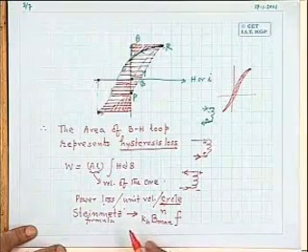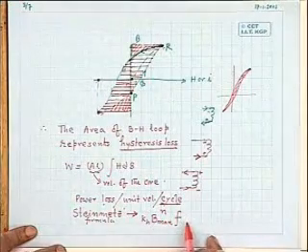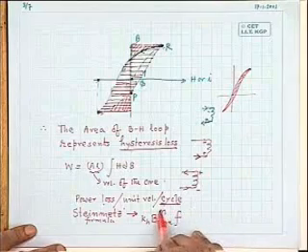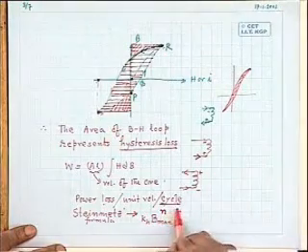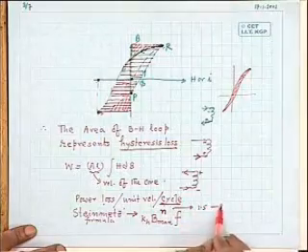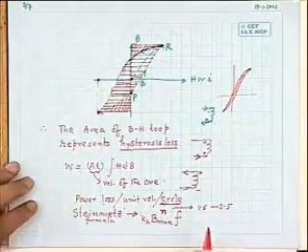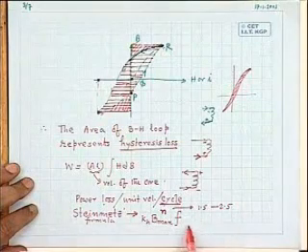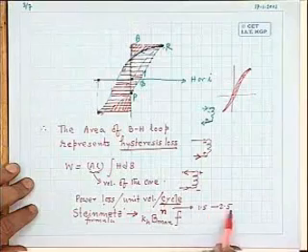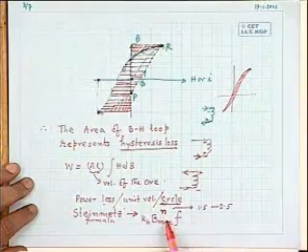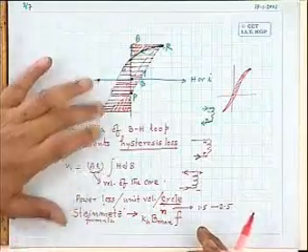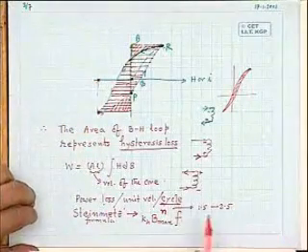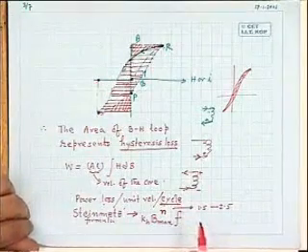What are these formulas called, which are not derived? Some empirical formula, you are right. So it is an empirical formula he suggested, and he told that this Kh will be a constant of the material, and this n can be between say 1.5 to 2.5 depending upon the types of material. And f is the supply frequency. One can use this also to calculate this hysteresis loss without obtaining the BH loop. And what he is ultimately suggesting is that the difference, if you calculate in this way, will not be much. This was obtained after doing several experiments on different kinds of materials.